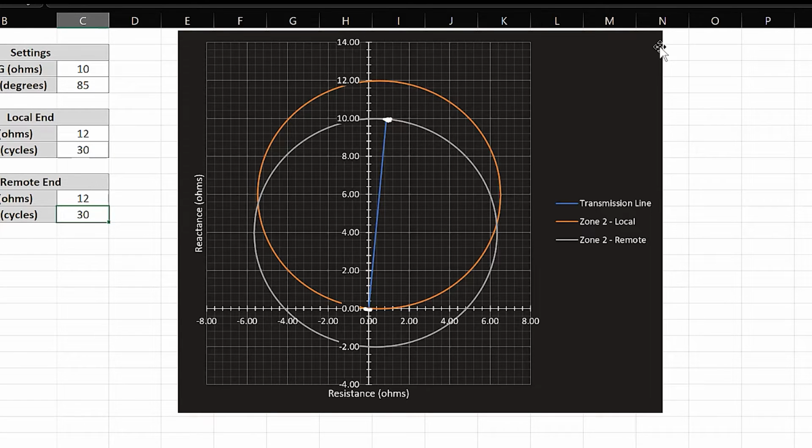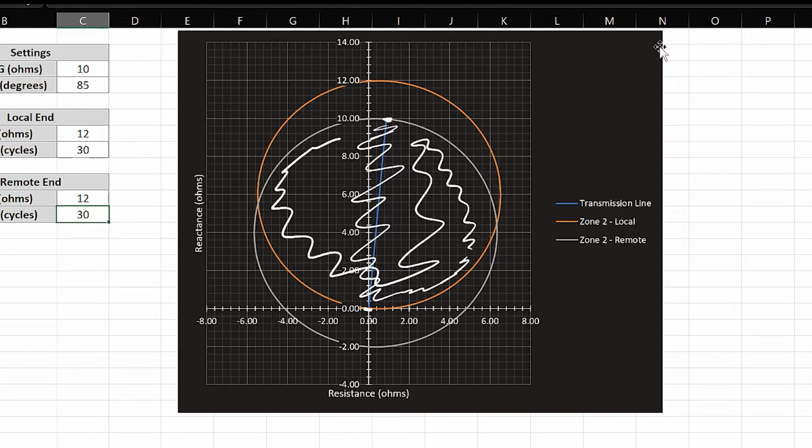So basically, again, here, the zone where our high-speed tripping would happen is where these two zones overlap. So basically, this area over here, where again, you can see that the two circles overlap with each other. Now note here that it is also important to include some overlap so that we can detect any fault in the transmission line, including any potential fault resistance or fault impedance.